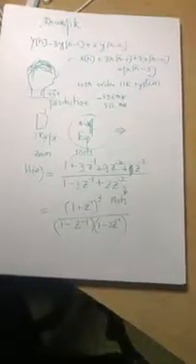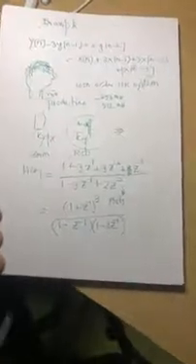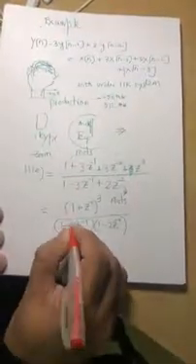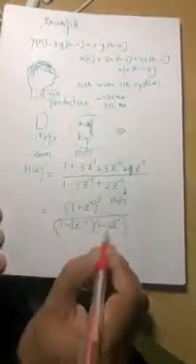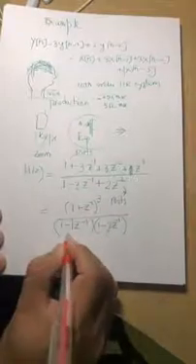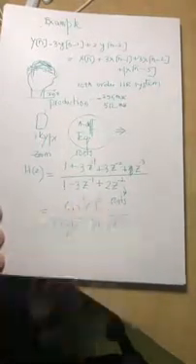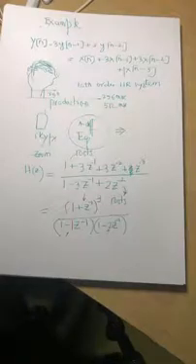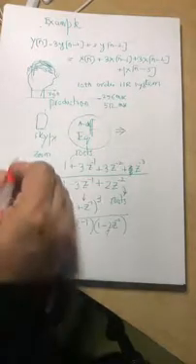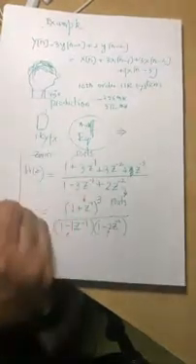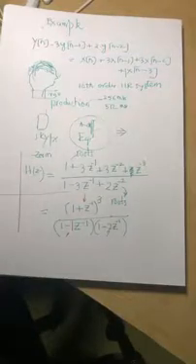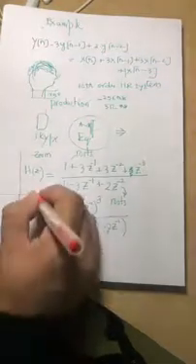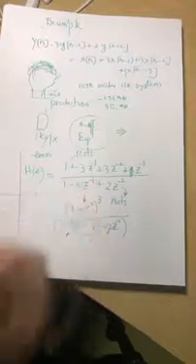So what are the poles and zeros? We know that it has a pole at 1, a pole at 2, and 3 zeros at minus 1. So you need to draw these. Let me plot this. There is a pole at 1, and right away you know that this is an unstable system.